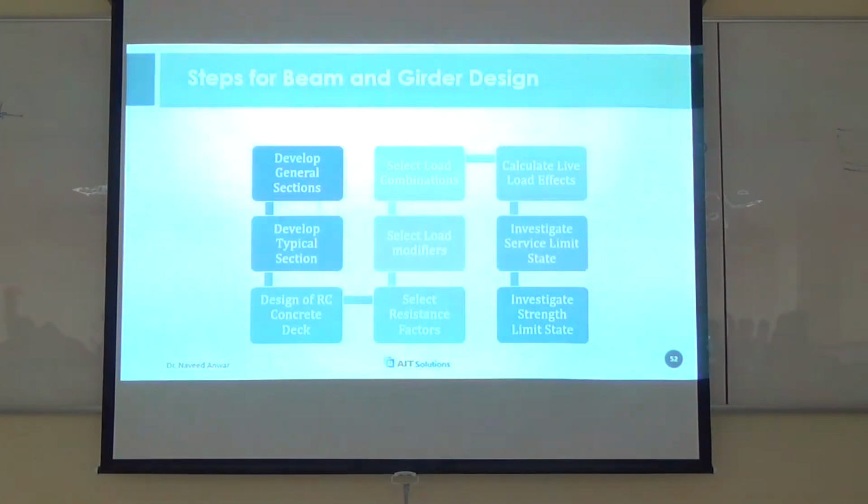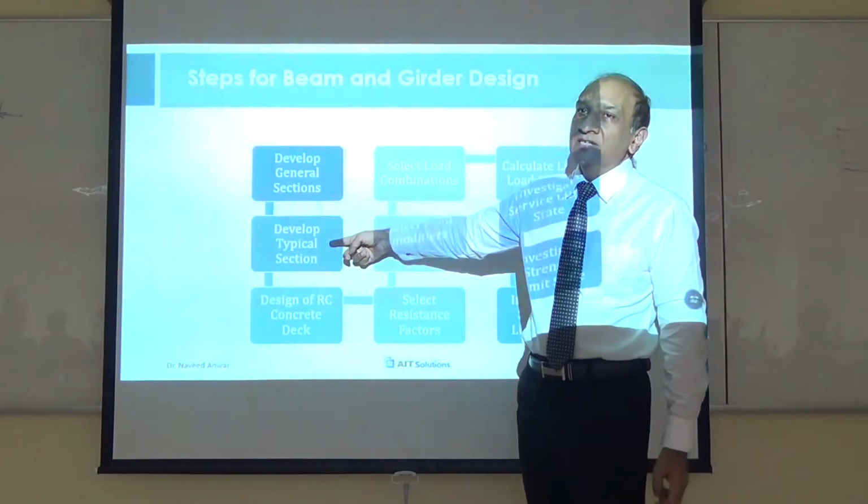So this 2-span repeated 20 times, I will model it 1 time. This one. So you divide the overall bridge into typical parts that will be repeated many times. In a bridge outside the city, mostly it can be typical. A bridge within the city, typical is difficult because everything is different. You have seen the bridges have to move up and down, so typical is very difficult. But normally we try to identify what elements are typical.